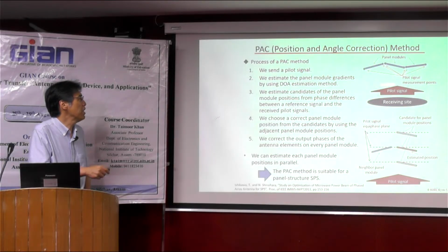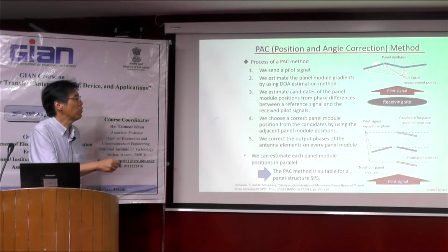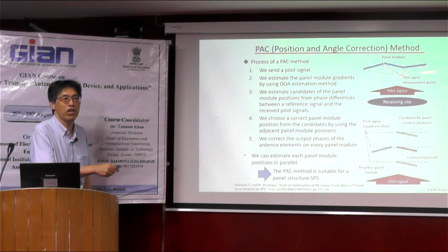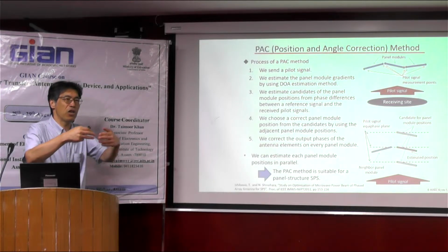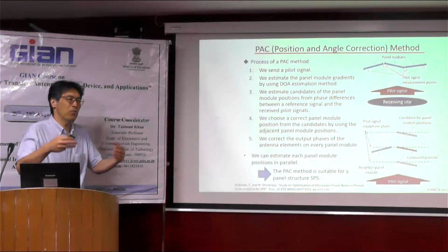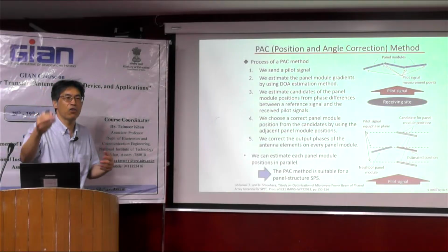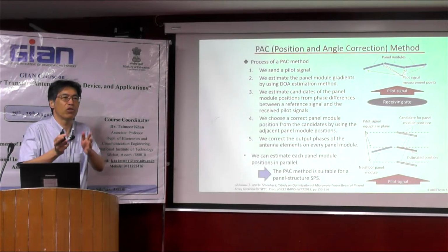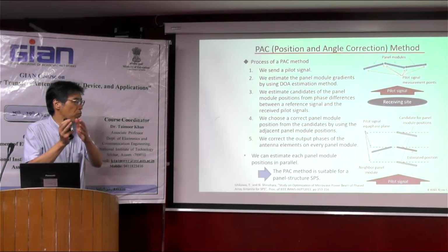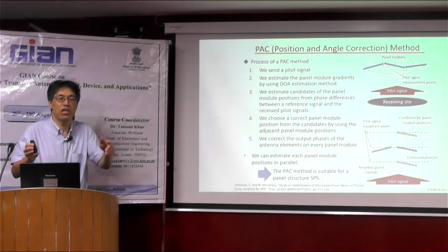And in this PAC method, we use a similar closed loop, and it involves the data of the shape of the antenna, like this. If the antenna shape is strange, even if we know the target position, we cannot control the beam direction, because we have to control the optimum phase in each antenna position.